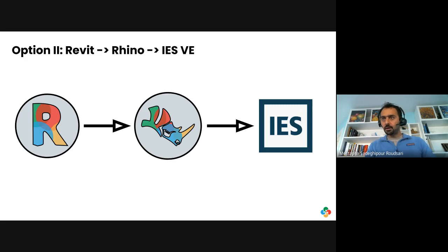Is there a way to reduce the surfaces on shadings? For example, models that come with louvers, and every window will have thousands of surfaces that make the IES model heavier. Yes, for those, do not select those shades from Revit, or just select one face, because it's not like we export all the shades, right?